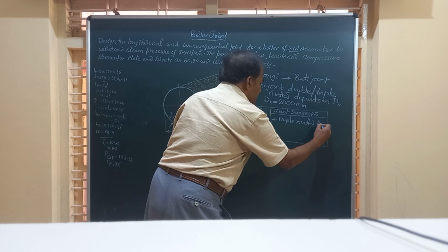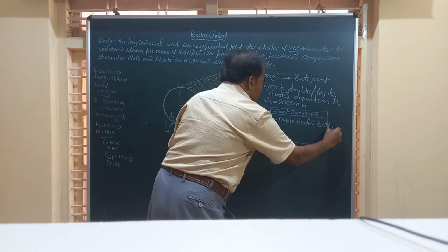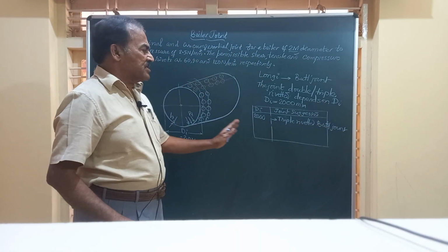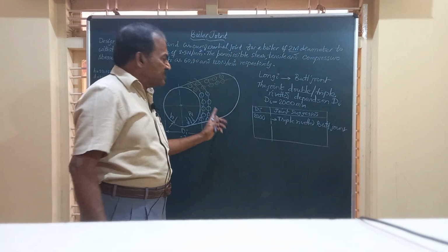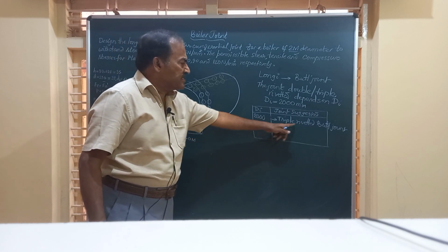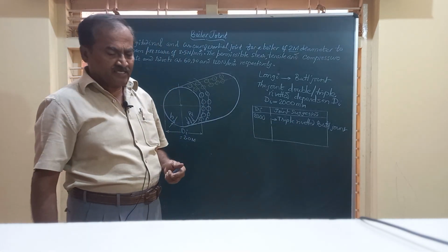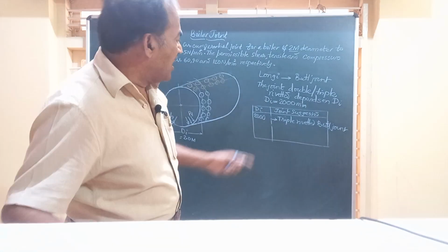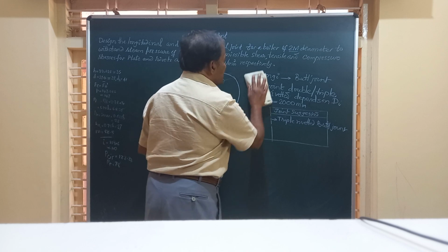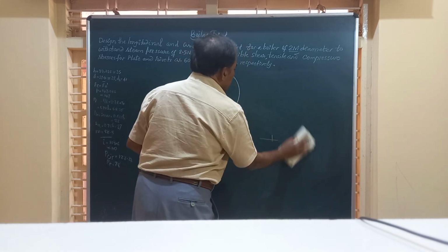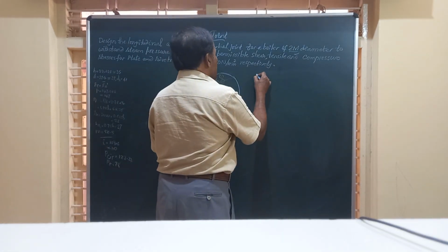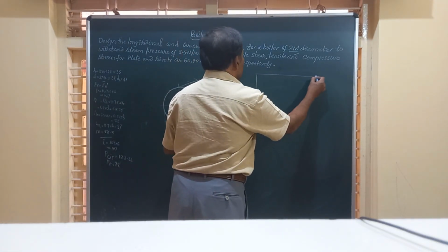It's a butt joint, so triple riveted butt joint. You have to first of all find out what the joint is. For this range up to 2000 millimeter, the triple riveted butt joint is suggested. And after knowing the type of joint, that is triple riveted joint, there is another table which will give the efficiency.